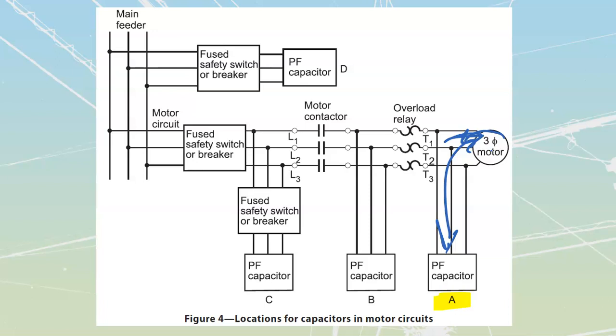Just, the inductor has it and the capacitor has it, etc. But if I'm only passing that current back and forth over top of these lines, that means all that extra current does not have to go over any of the rest of the lines inside of my installation. This means that I'm going to have the lowest value of current coming into my motor, and I'm going to have the least amount of line loss and line drop to it.